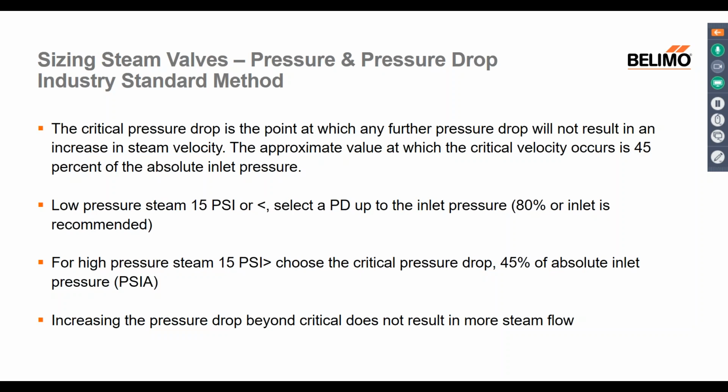The definition of low pressure steam is below 15 psi. Low pressure steam is pressure psig below 15 psi. And it's always handy to remember, steam pressure is totally related to steam temperature, for saturated steam. 15 psi, 250 degrees. Very easy to remember.